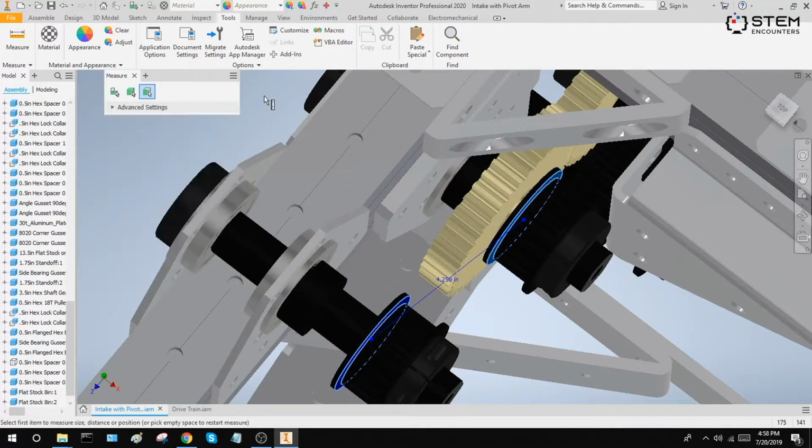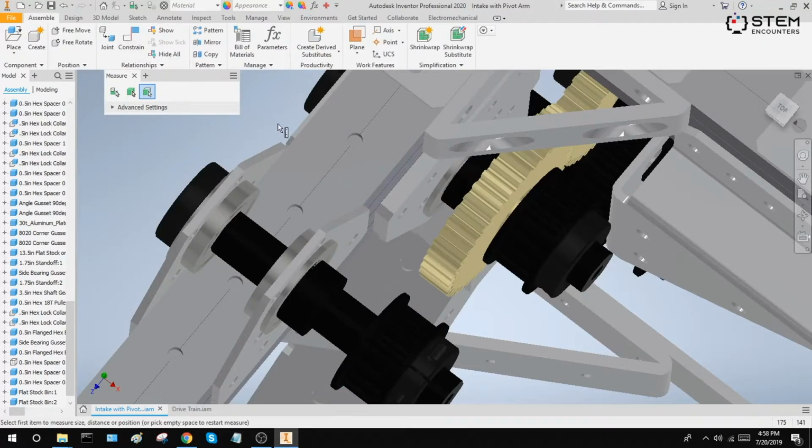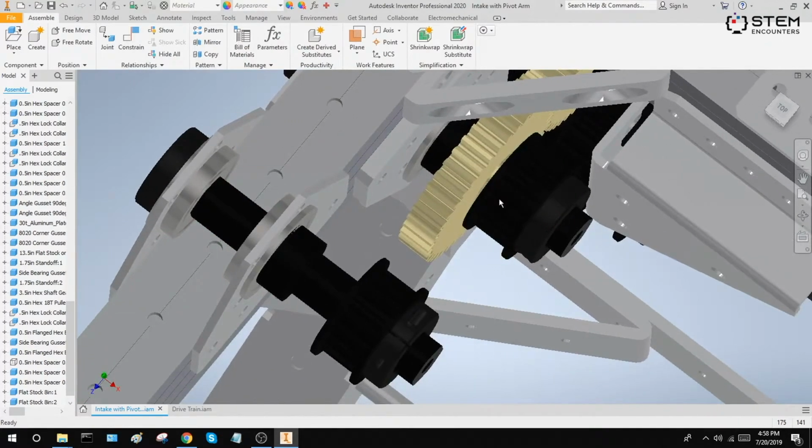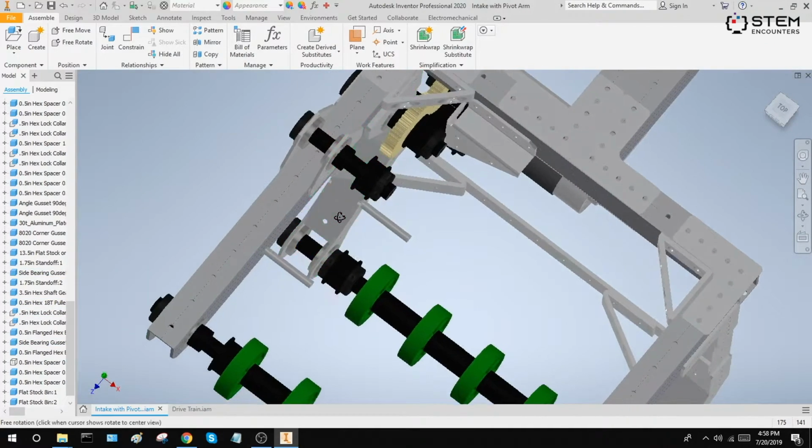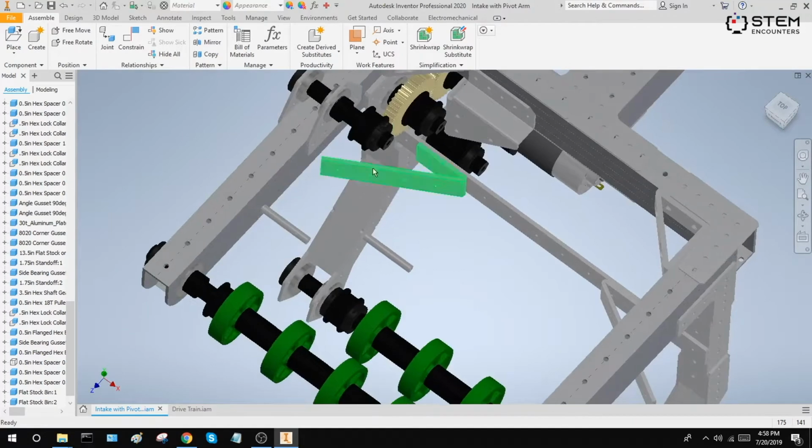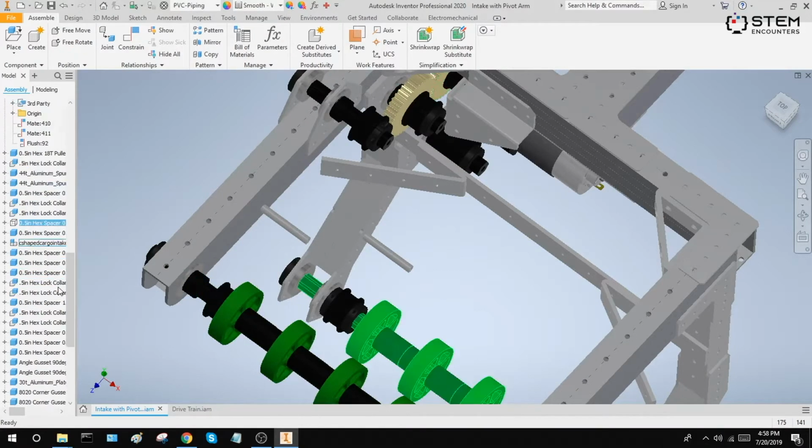If that's the case, that's fine. Just try to minimize it because there is some tolerance in how the belt runs along the pulley. But if possible, always use a flush constraint for pulleys and chain and sprockets. This is especially important in sprockets where there's less tolerance because the chain has to mesh on the teeth of the sprocket.